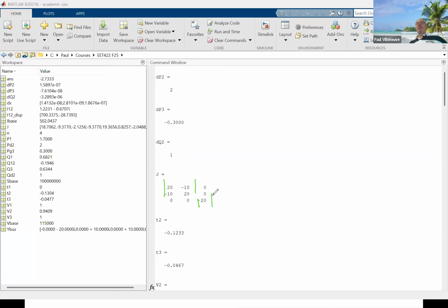And that's one way to speed up the results. If you don't want to update the Jacobian every time, sometimes you can just use your Y bus values and go through that. That's called a fast decoupled method. It does it really quickly, but it may not necessarily be accurate. You used to see a lot more of that work back in the day, but you don't see it much anymore because, with parallel processing, you can do a lot of this stuff quickly.